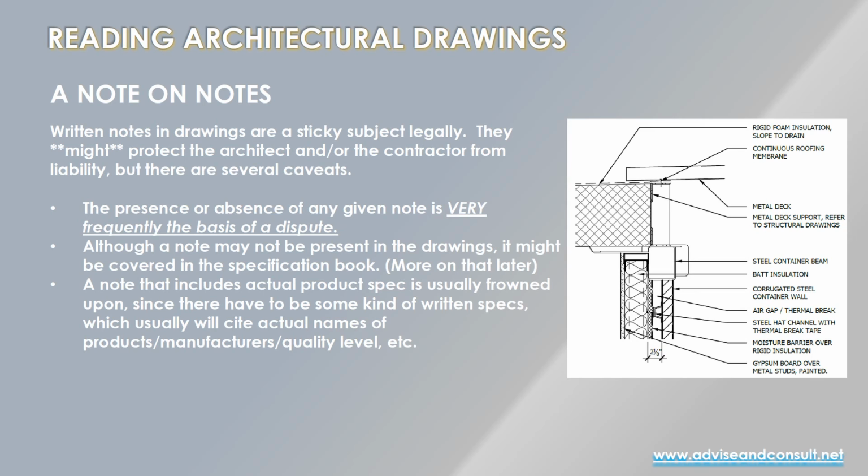A note on notes. Verbal notes in architectural drawings, the presence or absence of the note is almost invariably a component of a construction dispute. So for example, here we say metal deck and metal deck support refer to structural drawings.